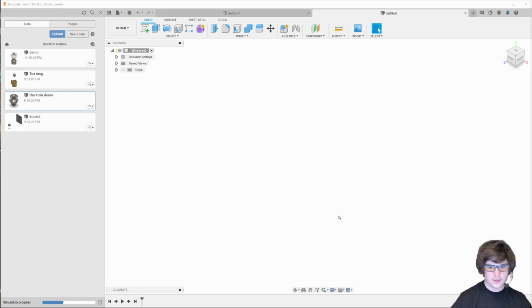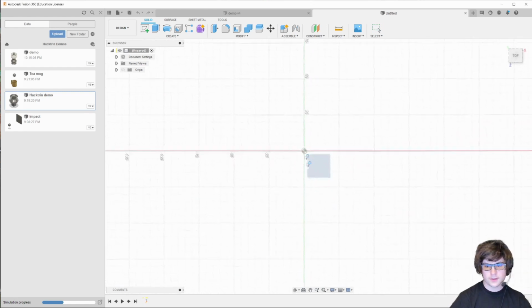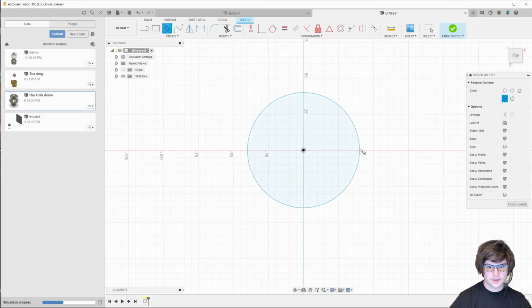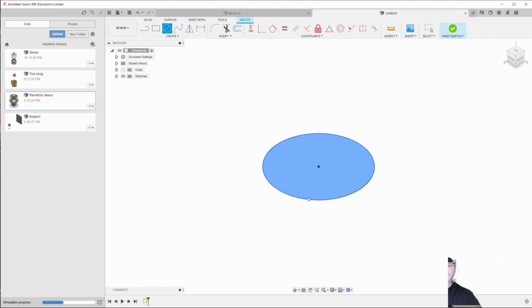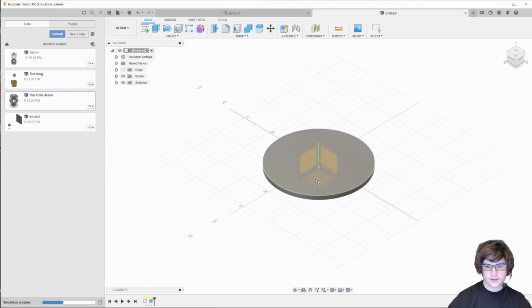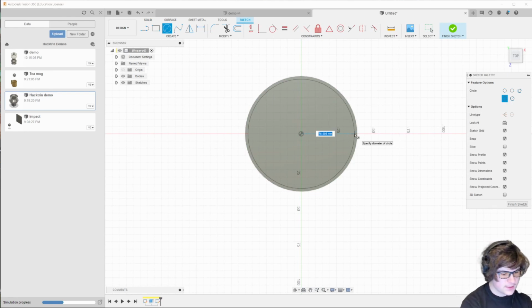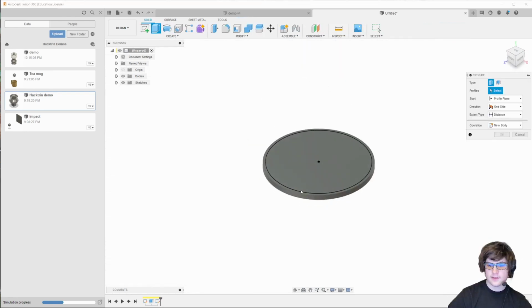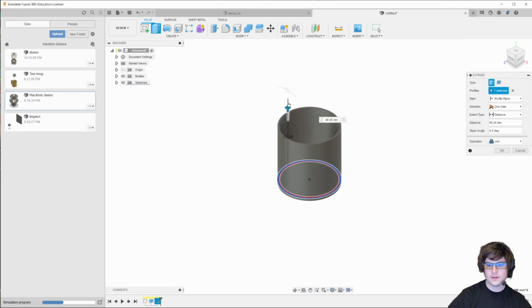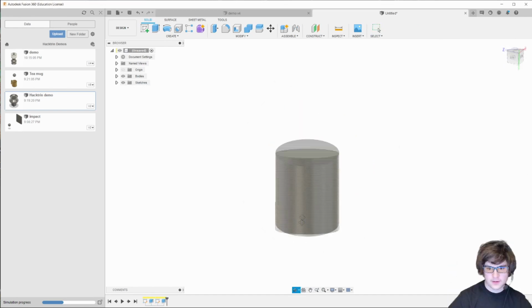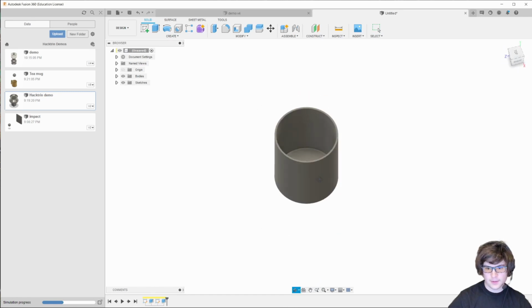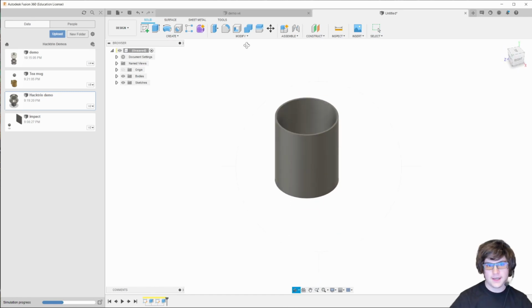So what I'm going to do is create a circle. Let's make it 80 millimeters, and I'm going to add some thickness to it, make it 4, add another circle on top, which will give me my inner and outer walls. Let's make this 76 millimeters, add some thickness. That looks like about the right proportions. And then we have basically a mug, but you obviously need a handle.